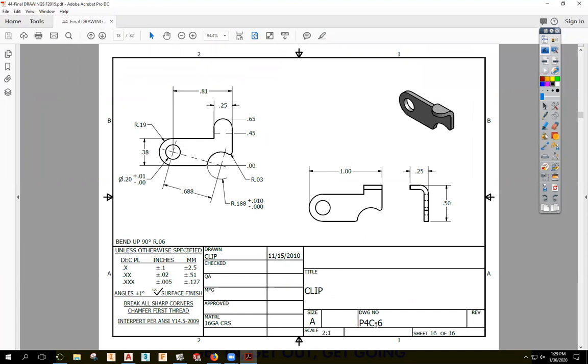So is it just holes? Can it be square? Yeah. So if you have a dimension that goes between two things, it's not just coming from the edge over. It means that those two things have to be related to each other that same way.